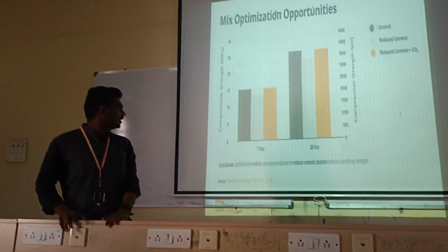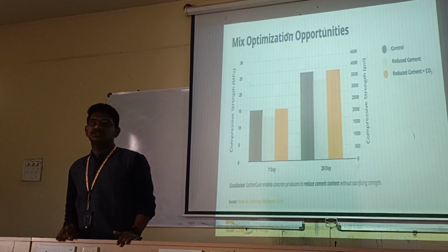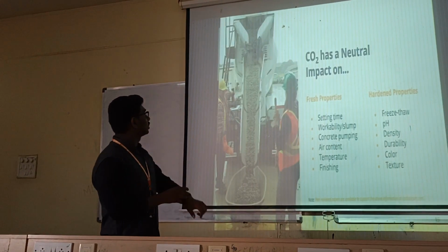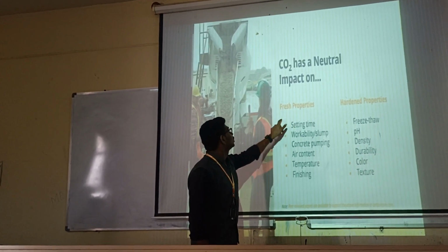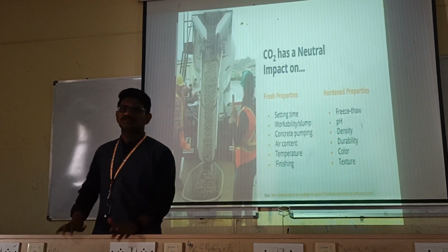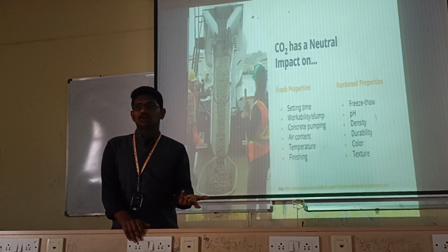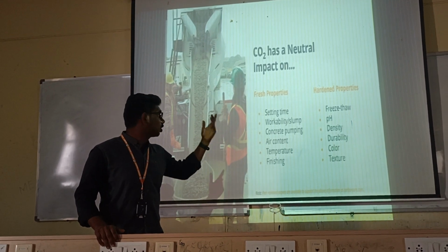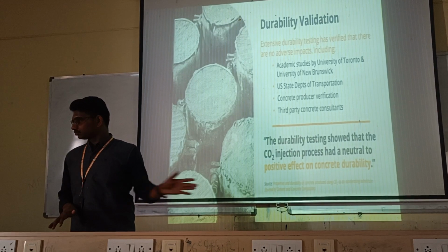And we can also say that it is statistically proven that 3 to 7% of compressive strength is gained by using CCT. Next slide, please. Injection of CO2 has a neutral impact on concrete's fresh and hardened properties. All the other properties of concrete, like pH, setting of the concrete, hydration, air content, temperature, texture, will not be affected. So there's no negative impact on it.